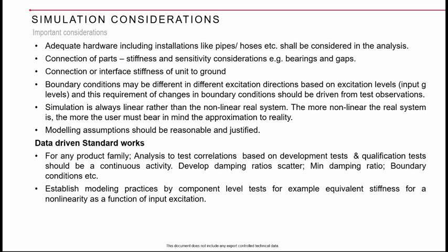Okay, some key aspects. I think we already discussed many of these. One important thing is you have to remember that your simulation is always linear, whereas real systems are nonlinear. So the more nonlinear the real system is, you should keep in mind that whatever approximations you are making may not be closer to reality, and you may have to revisit them when you go for test correlations. So all the modeling assumptions should be reasonable and should be justified ahead.